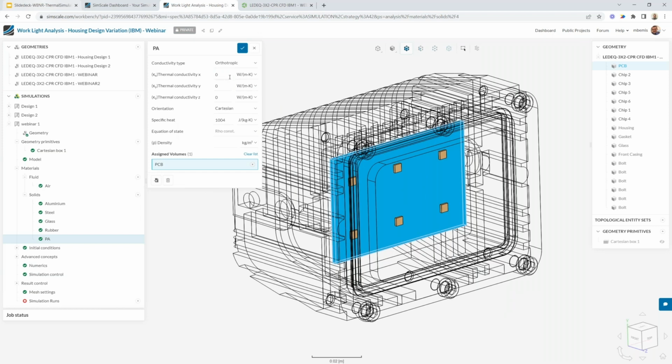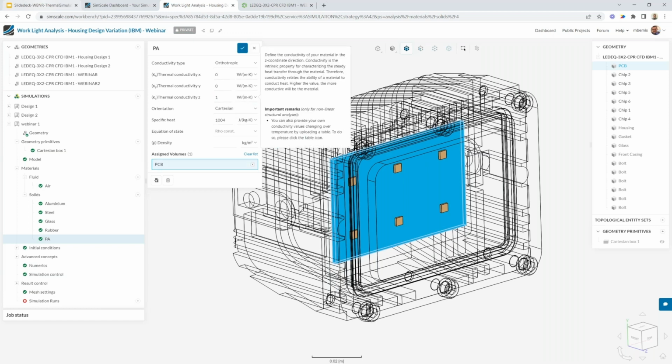Z. Now, this is very important because based on the layers of FR4 and copper, the material properties change based on direction. So actually in the in-plane direction, in this case, looking at the Cartesian coordinate system in the lower right corner, X and Y, there's very high thermal conductivity. A lot of times it comes out to around, say, 20, whereas in the through direction, it's much lower, maybe closer to 1.